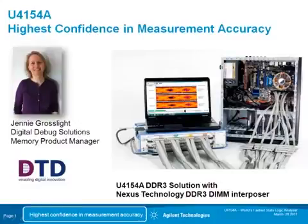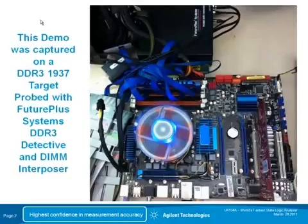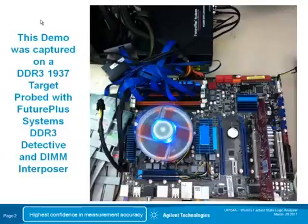Jenny Grosslight, here to introduce Agilent's new U4154A 4 gigabit per second state mode logic analyzer, capable of capturing signals with data valid windows as small as 100 picoseconds by 100 millivolts at the probe point, providing you the highest confidence in measurement accuracy. Our target for this demonstration is a DDR3 desktop operating just under 2 gigabits per second.